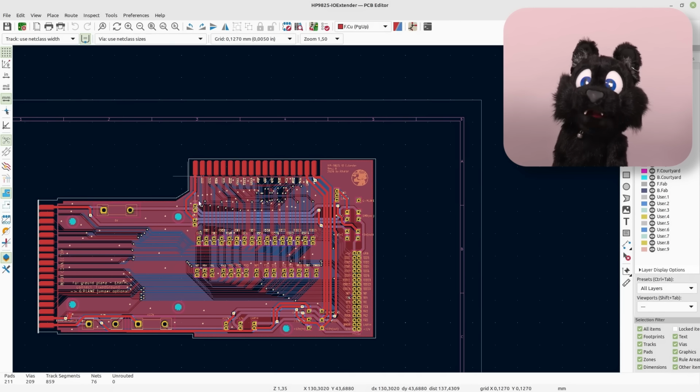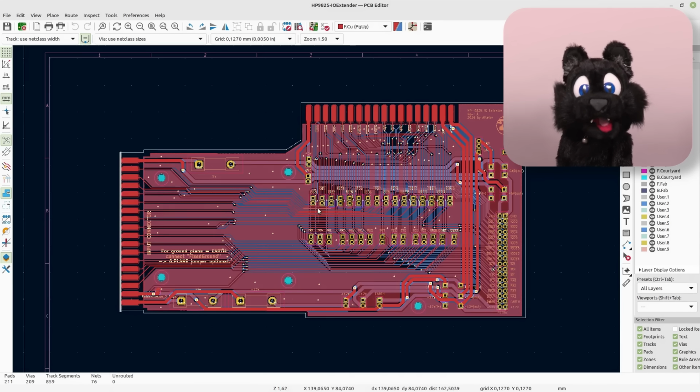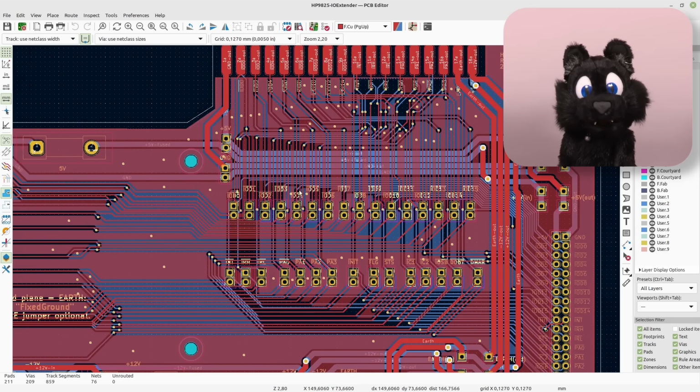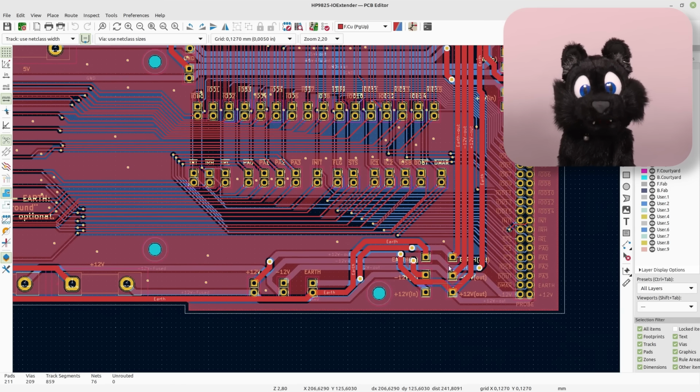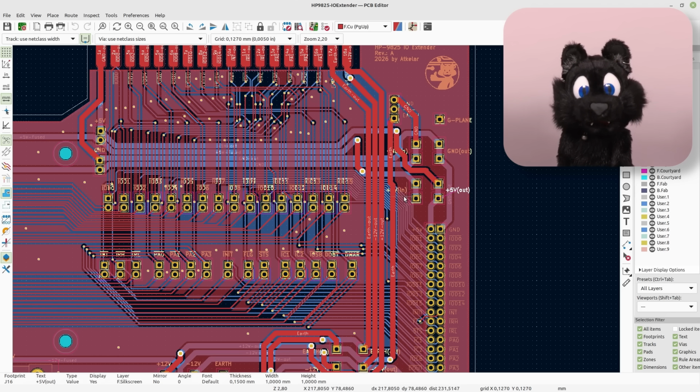And tada! The outlines took a bit of measuring and estimation time, but here we are. I put the jumpers into grouped positions. 5 volt and ground here, 12 volt and earth down there. Connection points for the voltage rails have both pre and post jumpers labeled in and out connection points over here. If you pull the jumper, you can use these for current measuring, for example.